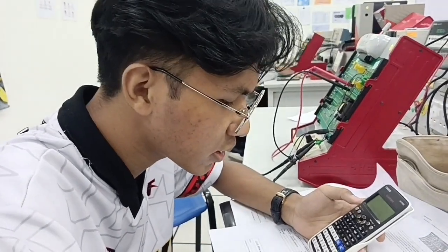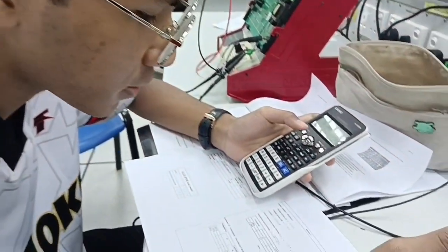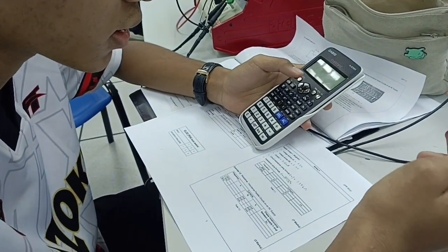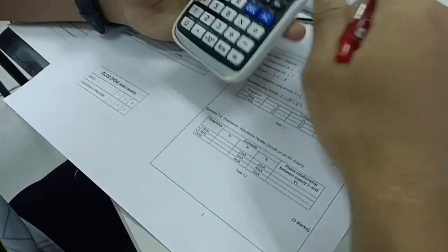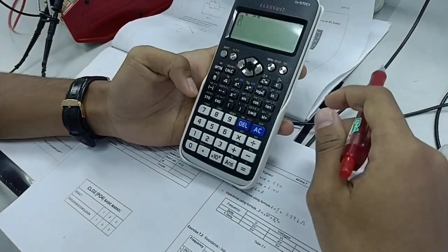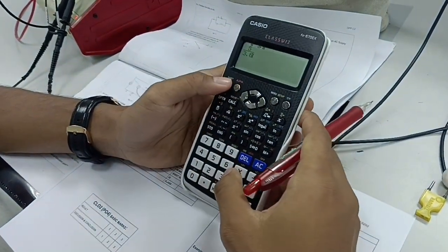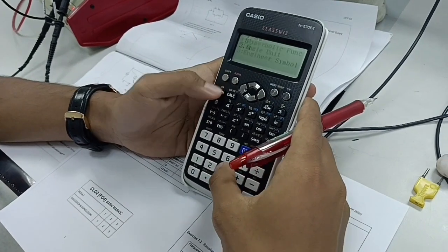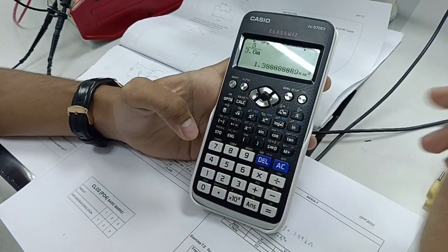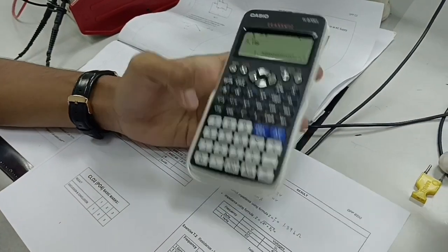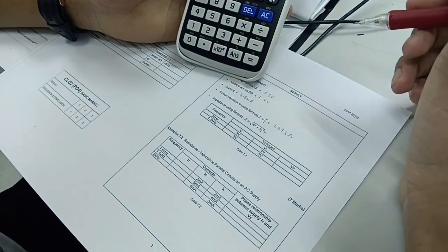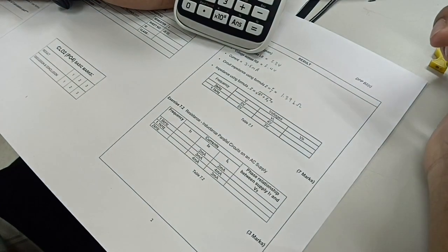Based on the result we get, we will search the impedance. The formula is given, which is voltage over current. Voltage is 5 volt and current is 3.6 milliampere. And the impedance we get is 1.39 kilo ohm. When we use the other formula, the result must be nearly the same as the first result. But the most important thing is we must search the XL first before using this formula.